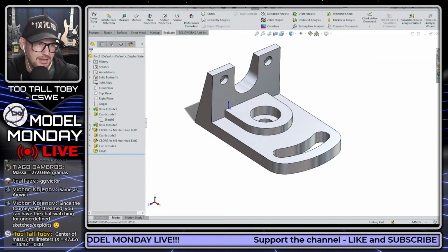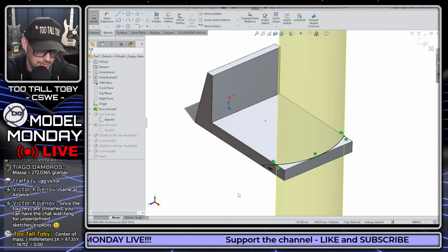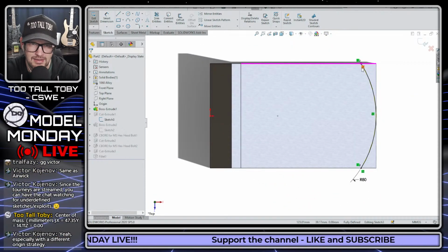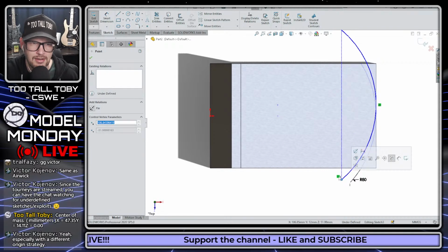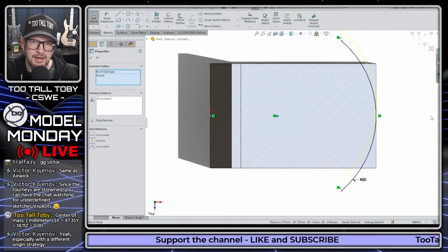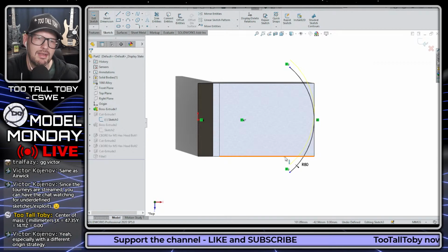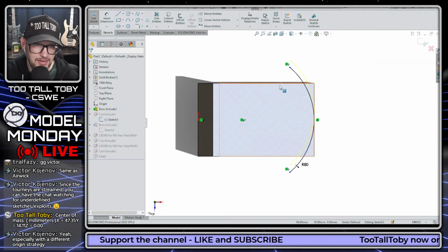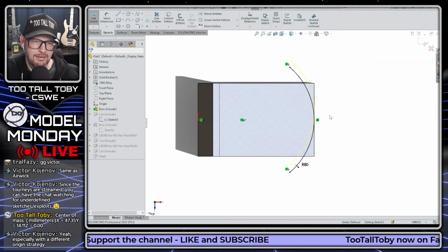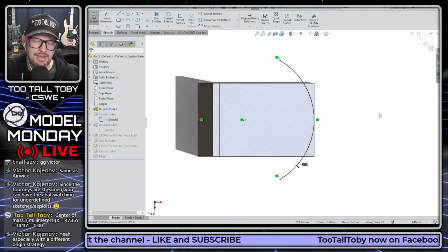There's going to be spots where, with a sketch like this, a lot of times, even in the production world, I might take a sketch like this and not necessarily have it fully defined on these edges here, and instead just have this horizontal here. There might be a reason. I'm worried that I'm going to lose this edge because adding a fillet to this edge could affect the edge ID downstream. So I might leave it arbitrarily wide here and not necessarily lock it down.